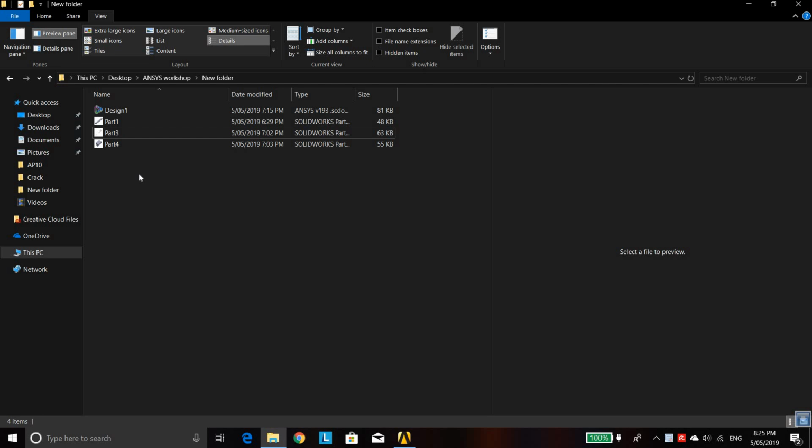Today I'm going to show you how we can have explicit dynamic analysis for investigating a bar made of concrete with some reinforcement. The reinforcing bars are going to be stainless steel, and the block is going to be concrete, and that block of concrete is going to be over two supports, and another object I'm going to use to apply force at the center.